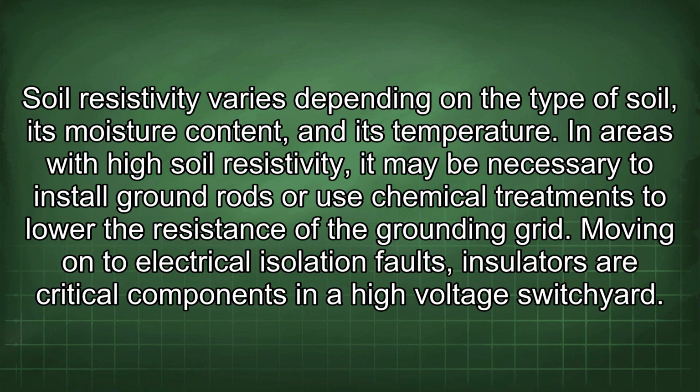Soil resistivity varies depending on the type of soil, its moisture content, and its temperature. In areas with high soil resistivity, it may be necessary to install ground rods or use chemical treatments to lower the resistance of the grounding grid.